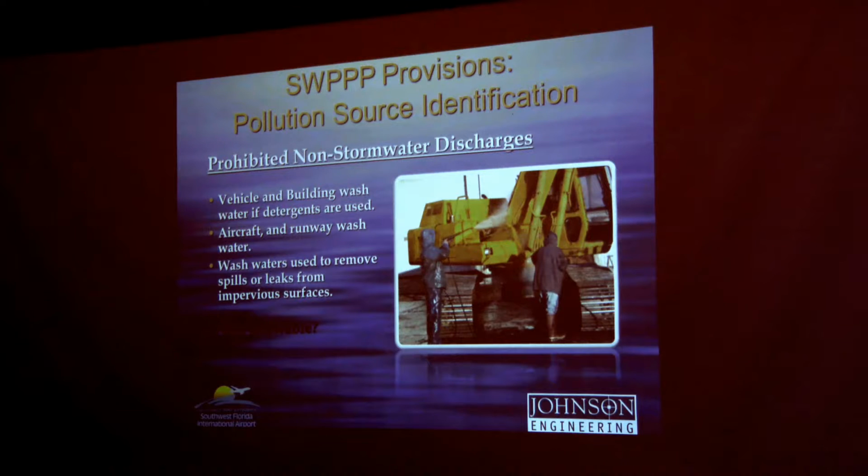Is this an allowable discharge of stormwater? Just throw it out. Anybody? No? Probably not. They're probably not, unless they're catching all of that water and treating it appropriately. And the reason is there's grease, there's oils on this piece of equipment that are going to get sprayed off and washed into the system.